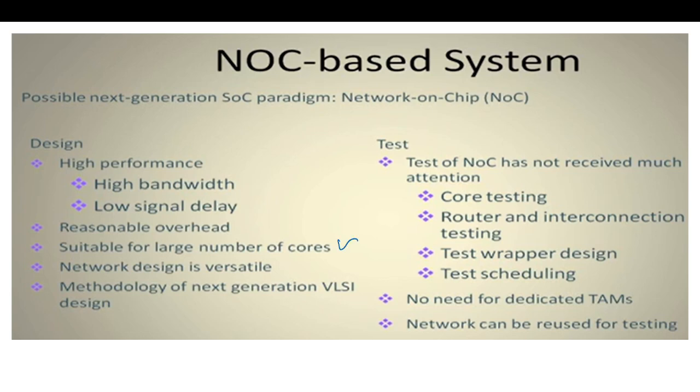If we keep adding more cores in a dedicated or point-to-point network, the interconnects will keep increasing, and in a system on chip the area is also limited. With a shared bus architecture, we can't keep adding cores because it will degrade the performance of the bus. So NOC is suitable for a large number of cores.